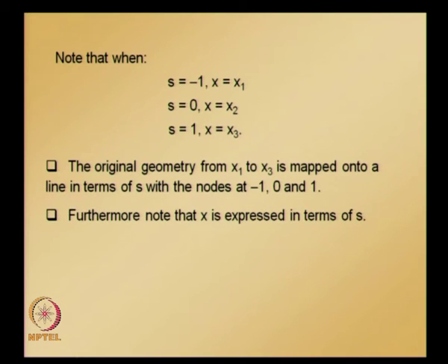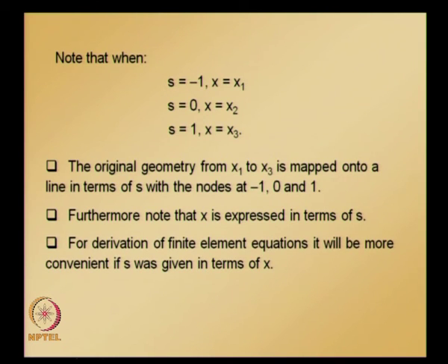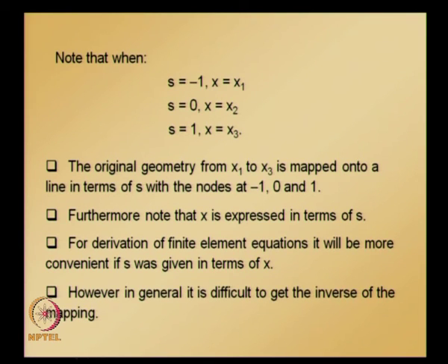Furthermore, note that x is expressed in terms of s. For derivation of finite element equations, it will be more convenient if we have s in terms of x. However, in general it is difficult to get the inverse mapping.